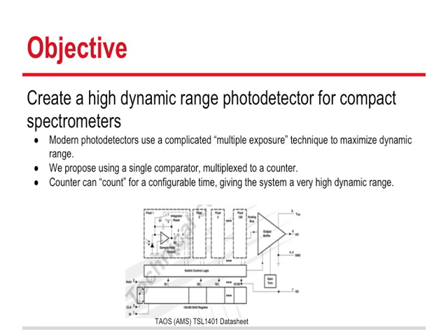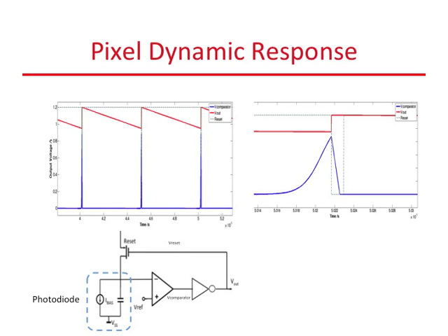If the exposure time is incorrectly estimated or the difference between the bright and dark pixels is large, however, the net dynamic range is compromised and the full range is not realized. Overexposure or saturation can also lead to blooming and contribute noise to neighboring pixels. With our circuit, we are able to simplify and improve the current photodetector design using the following methodology.